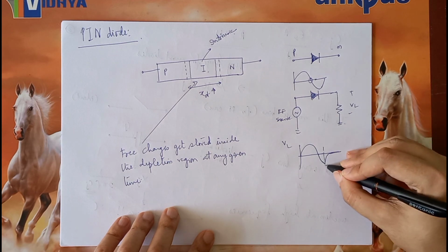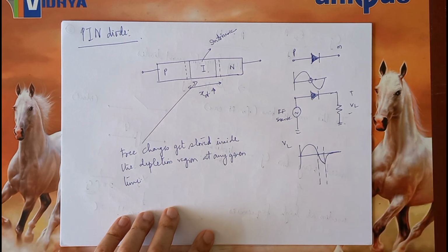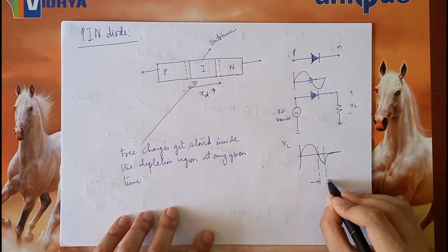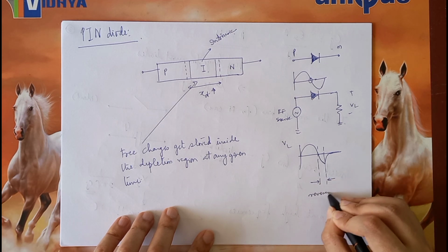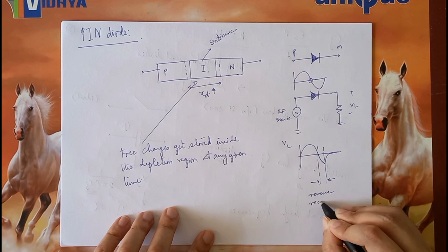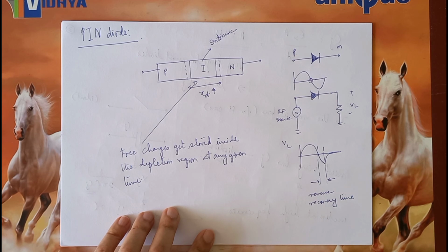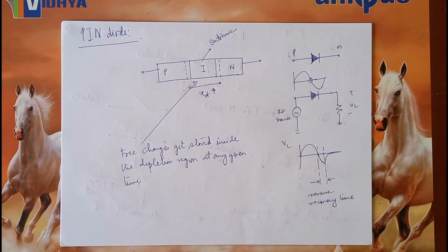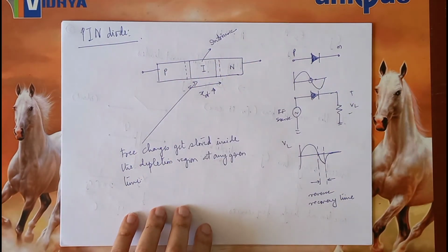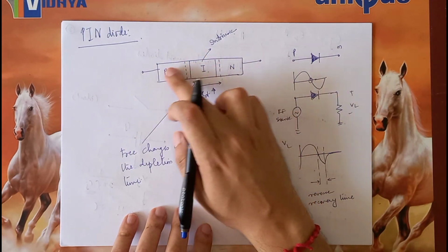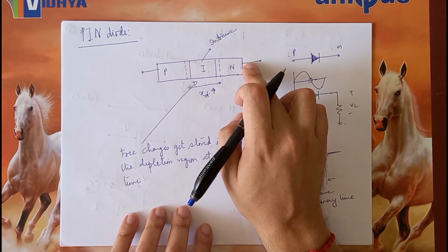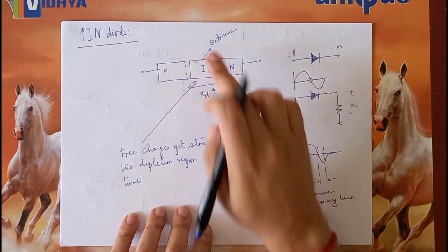So this time when the diode is still on is called the reverse recovery time. Here it indicates the time the trapped carriers take to recombine with each other or somewhere around. So in case some of the charges go over here or here, they manage to escape, very good. Otherwise they will recombine over here itself.